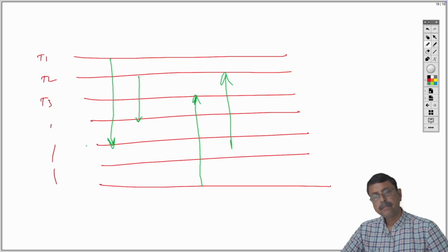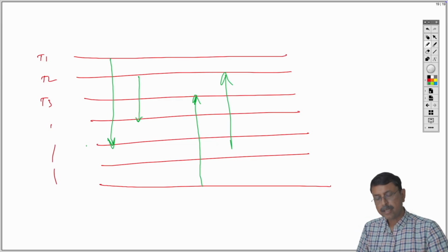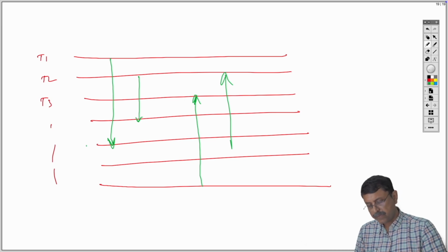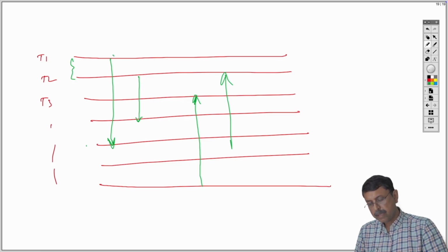Next cold stream, the temperature rises from this point to this point, and so on. So all the process streams you can represent on this chart within the parallel lines of temperature. Now you have to count the total heat content within each and every temperature gap. So suppose in the first temperature gap, we have only one stream that is active over here.